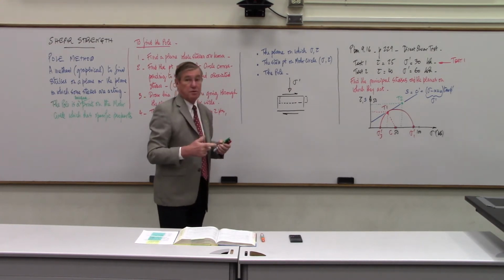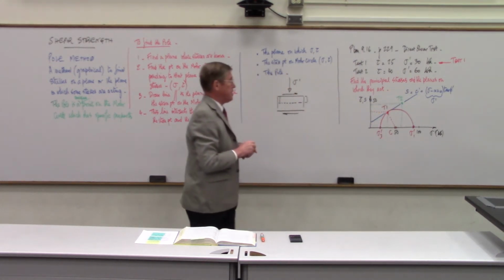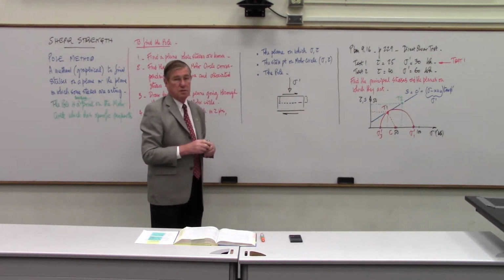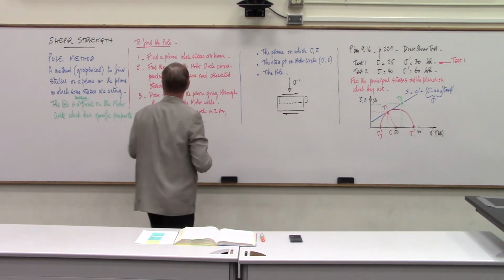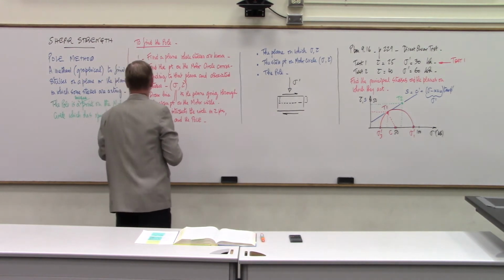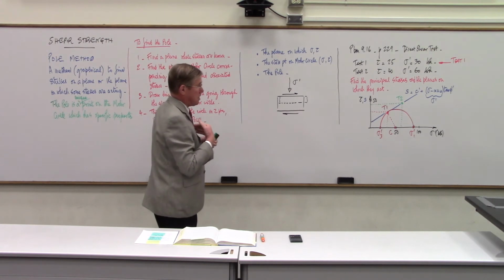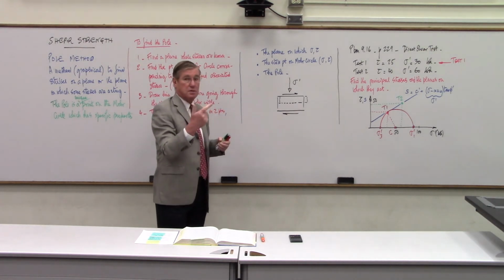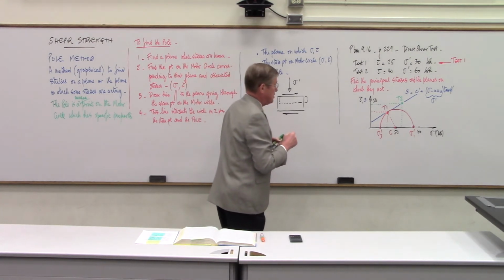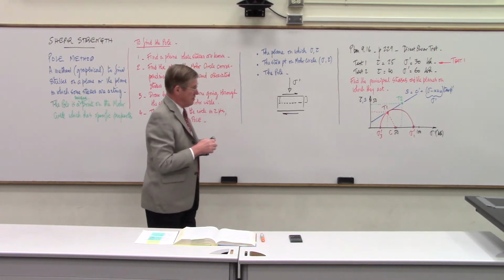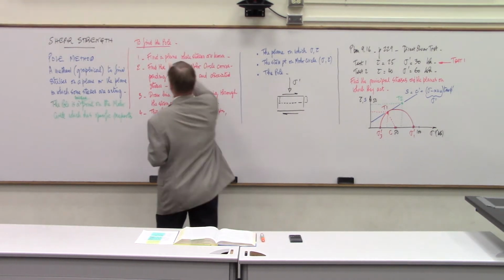Now the second part of the question is, what planes are the planes on which these normal stresses are acting? The pole method is a typical graphical method to find stresses on a plane or the plane associated with stresses. In this case, we know the stresses, sigma prime 1 and sigma prime 3, but we want to find what planes these stresses are acting on. So the first step is to find the pole.